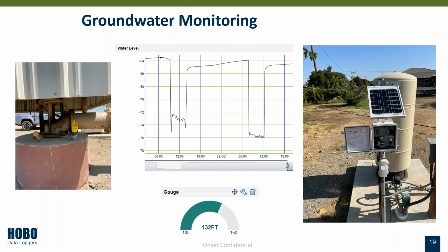One other thing that you're able to see is what your drawdown is like, right? If you're doing real time, you're going to be able to see how much the water draws down when you turn on your pump. So this is another great factor to know. You're able to know if your well is safe, if you have enough water, right? If your water is getting so low and you know where your pump is set, you're able to indicate, okay, do I need to lengthen my well? Do I need to do any type of changes?